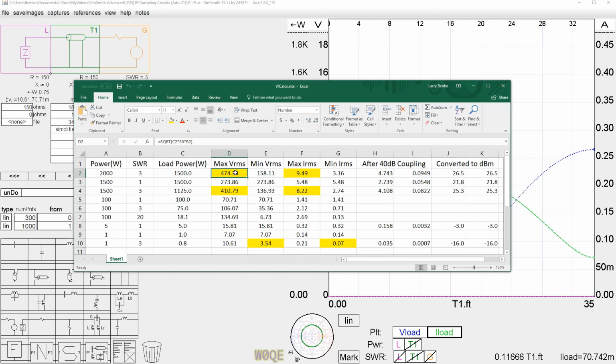If we take these signals and we want to do something to them, our monitoring circuit should take a fraction of the signal that we see and send it out to a port where we can put our receiver, our spectrum analyzer, our oscilloscope, or whatever. In this case, I decided let's do 40 dB. 40 dB has a really nice characteristic. It's 1/10,000th in power, but it's also 1/100th in voltage and 1/100th in current. So it calculates in your head very nicely.